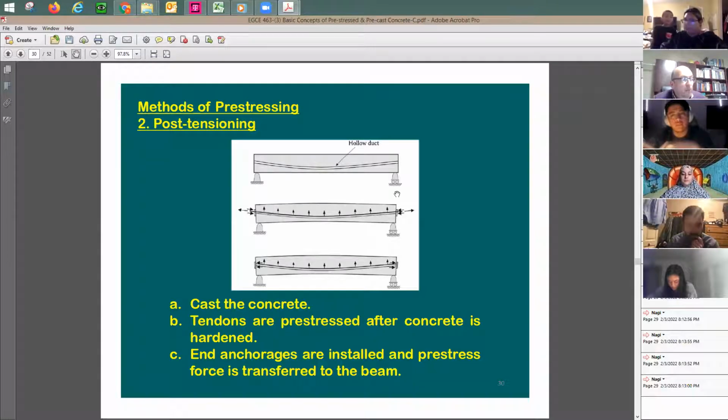So when you put the duct, you put it with the strand. Actually, when you buy the duct, it comes with a strand, and it comes greased from inside so that it won't rust. And then you put the duct and the strand before you cast the concrete. You put it in place and you secure it. You anchor it very well to the form, because you want it to take this drape or this shape, and then after that, you cast the concrete.